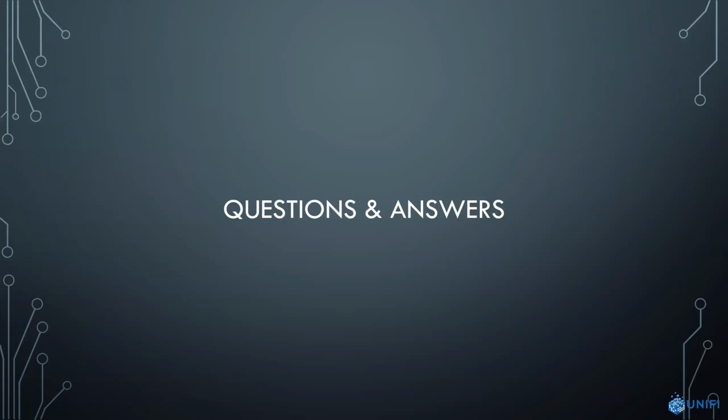So going back to the original question, what are some tips on sharing data across multiple models? I think copy monitoring is important because you can keep an eye on changes. Creating your own object, even though it's maybe not visible on plan view, to store your own data in is also another critical point. And then obviously making sure that the data is accurate in your model, because as firms look to adopt BIM or even just Revit, there can be bad data that surfaces as users try to tap into that data. So that's another thing to watch out for as well.